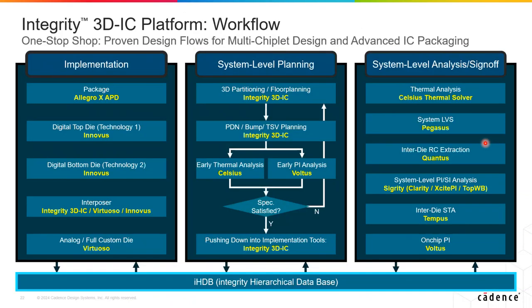So the overall design flow can be divided into three. The first is system level planning. For a good design and good development, we should have very good planning. So we need to decide which platform we use. We want to use just a simple flip chip BGA, or 2.5D, or multi-chip packaging. So we combine all the die information, package information, and substrate information, and do some 3D partitioning and flow planning. We do the planning of all the overall packages, how to connect, and how to optimize the die to die distance. Everything is planned in this step.